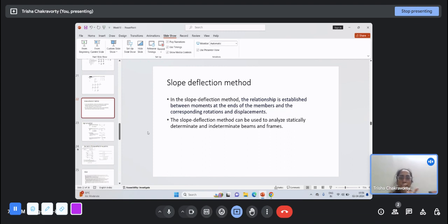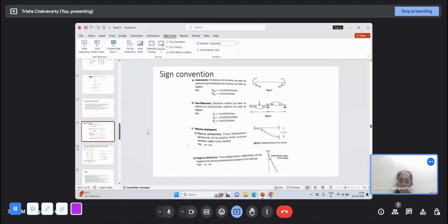Then we will go back to each segment. Now that we have the applied moments or the internal moments, we can find out the reactions, and then we have the entire loading pattern including reactions of the beam. Then we can draw the bending moment and shear force diagram, which is a continuous response of the structure. So that is how we end. And the sign convention is important.